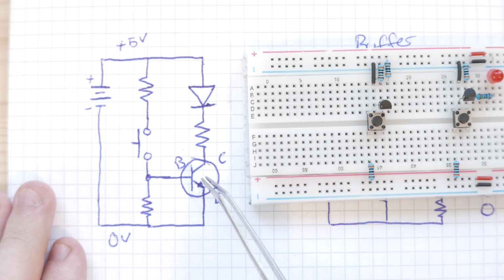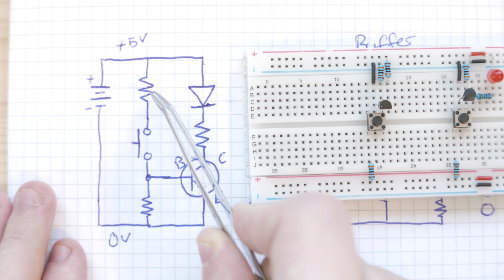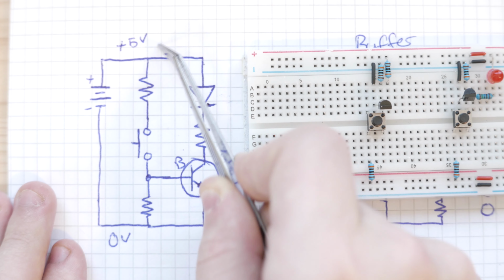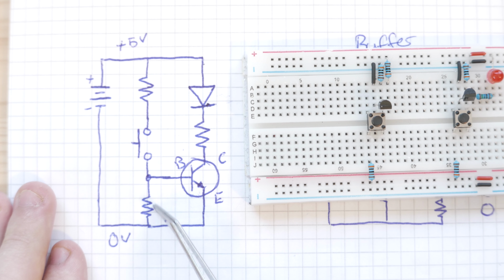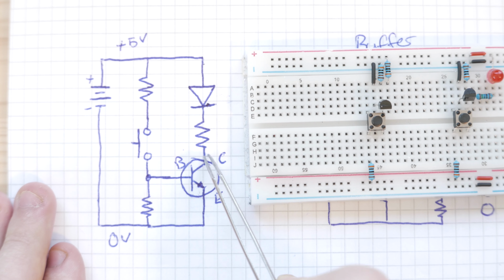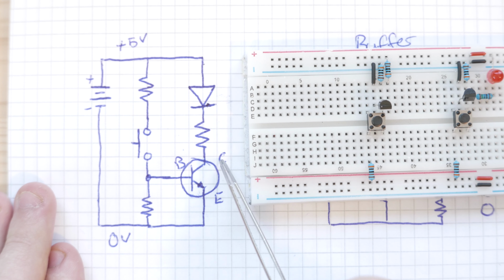So what I'm going to show you first is this little circuit here, and as you can see, when we flick this switch, it allows a current to flow through here and to ground. But since there's a resistor here, some of the current will want to go through the base of the transistor, which is the middle pin, and then through to the emitter, which is the leftmost pin in this case, and to ground. And what this does is that a current flowing from the base to the emitter allows a larger current to flow from the collector to the emitter.